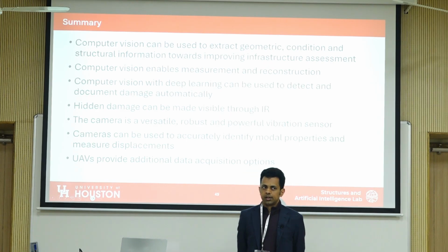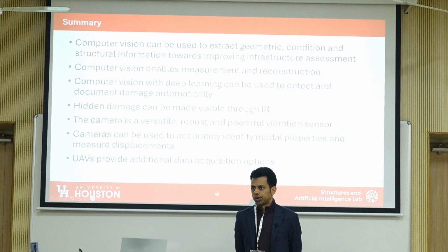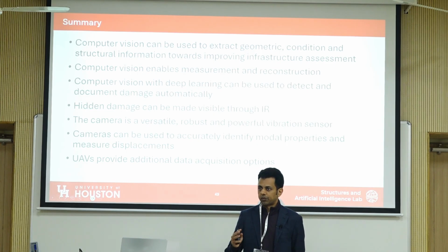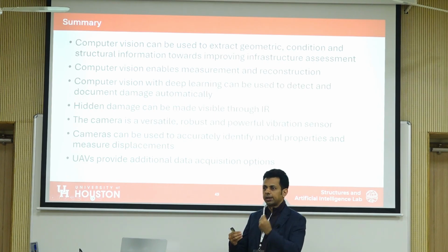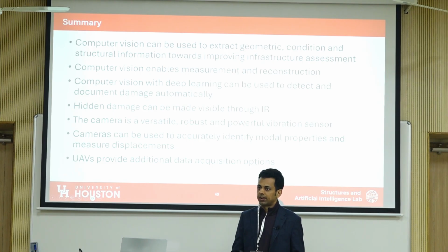In general, it depends on, again, what you're trying to do. If you're trying to do photogrammetry, one main step is matching features of the same object across multiple images. That means ideally you want the same feature to look the same from different images. Now, if you have a very large structure, it'll take you several hours to collect images of that structure.